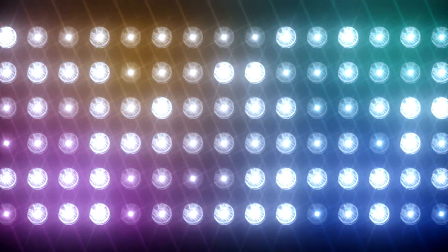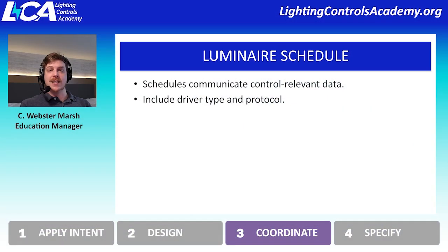So including that information in the luminaire schedule really does prevent issues later on, because if it's uncertain what resolution is being provided for that fixture, the wrong resolution might be selected, and the system might not be capable of controlling that many sections, that many segments within the luminaires. If you have dozens of these fixtures and they all have 1-foot resolution and you're only planning on 4-foot resolution. So that's a really important criteria. Just think through what is control relevant for this fixture.